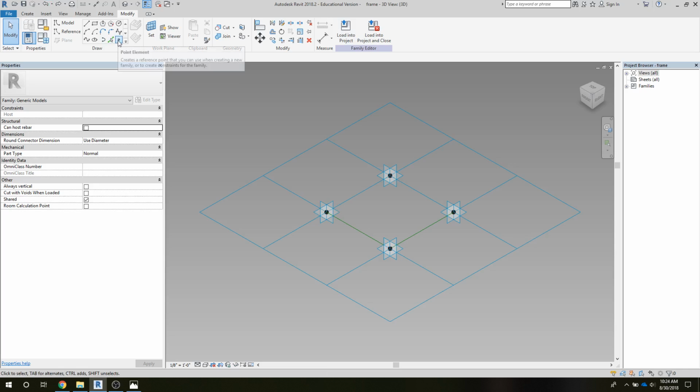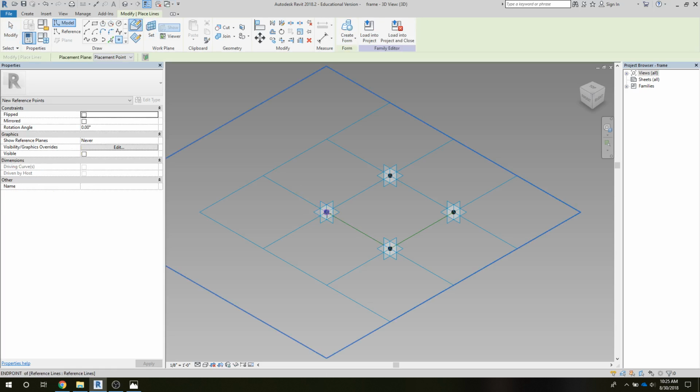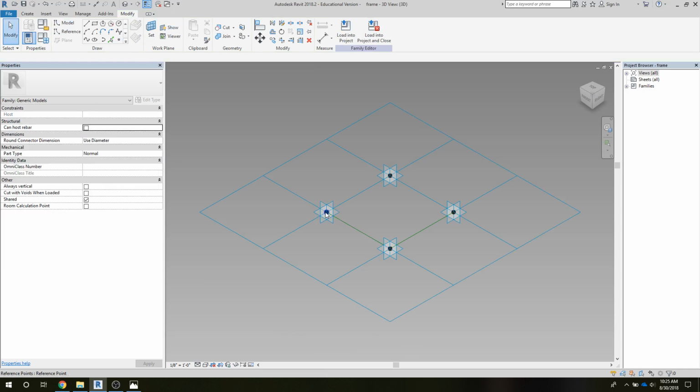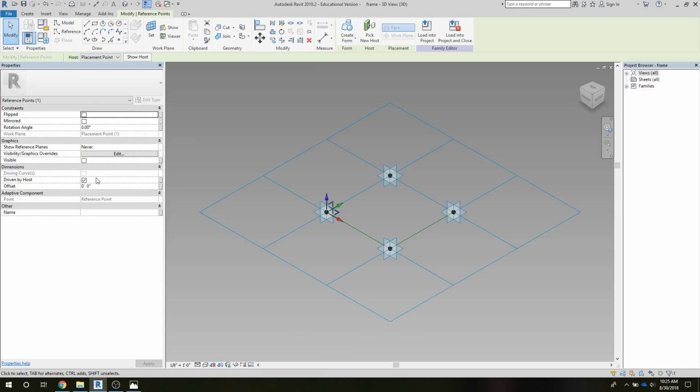So this technique is so common, you'll see hundreds of YouTube videos describing how to do this, but we're going to insert a bunch of adaptive points, a second tier of adaptive points that will behave exactly like the first points that we put in. And let me just demonstrate by actually putting one in. I'm going to identify that adaptive point by setting the reference plane. I'll do that one more time. Go in and click. Then I'm going to grab an adaptive point and place it here. And now if I come back in and touch that point, I can actually offset it.